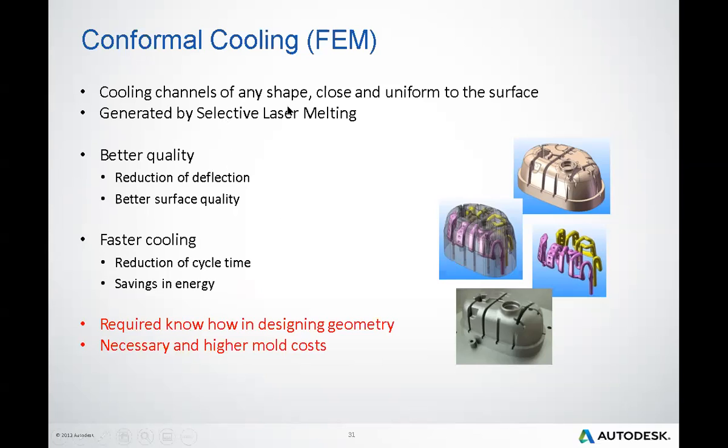So the cooling channel can be of any shape. If you have a complex shape, you can see that if we can make the cooling channel close to the part, it quite effectively extracts the heat from the part. You can see from here. But the complex shape of the cooling channel has to rely on a powerful CAD system, which Autodesk has invented, and Fusion 360 can help us to design the complex shape of the cooling channel. But the second problem is how to produce this.